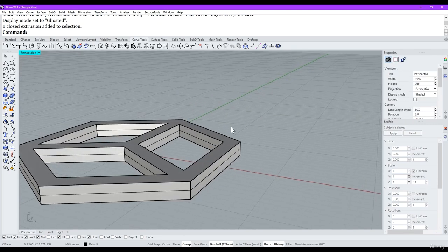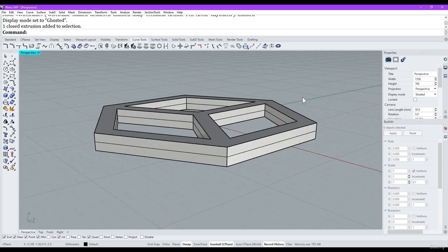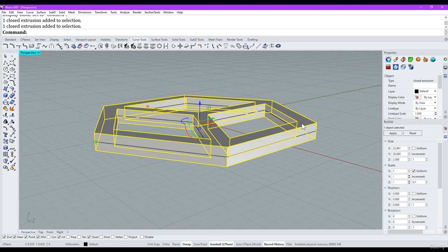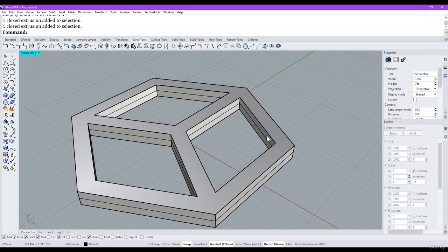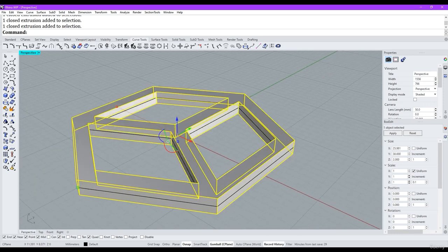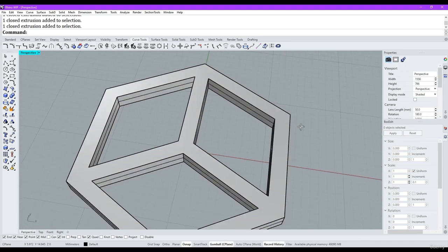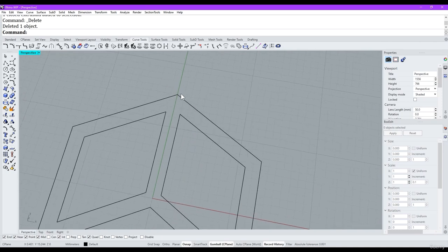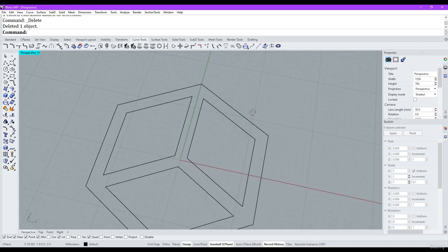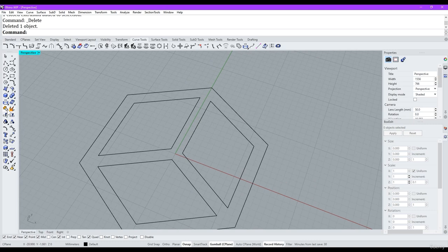Now Rhino is going to use extrusions where possible in order to save on space, and it's going to make things run a little bit faster. But normally we'd have each of these surfaces classified separately, and we would have something like a closed polysurface. So that's our pendant. Let's delete that, and I'll show you what happens when we don't have these joining up. Let's explode. We've got this little explosion icon here. So I'm going to explode this and press enter.